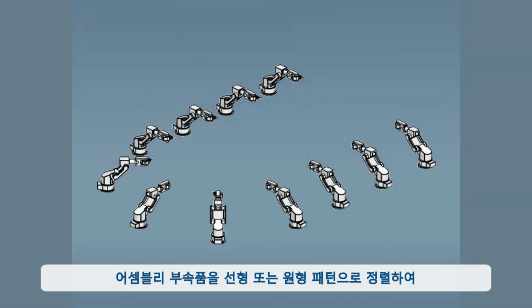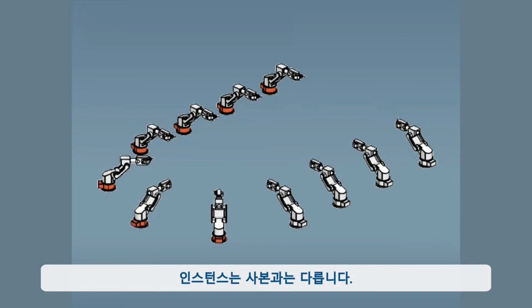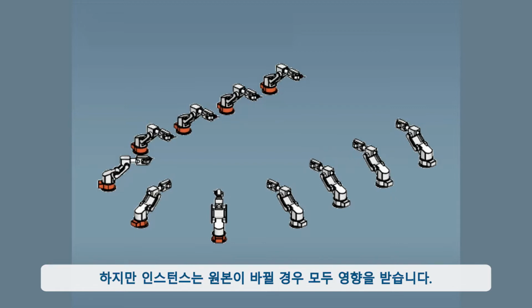We can create instances of assembly components, arranging them in linear or circular patterns. Instances are different than copies. Copies imply that changes to the original will have no effect on the copies. With instances, a change to the original will affect all of the instances.